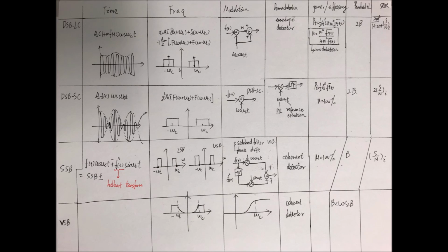Okay, my transmitter side will be a part of your large carrier, right? Just the signal mixed with a sinusoid, and we get double sideband suppressed carrier. So on the transmitter side, no extra work. However, for my demodulation, my demodulator will be much more complicated.